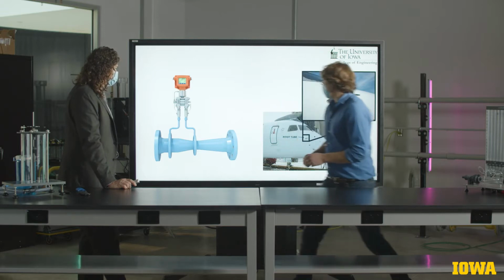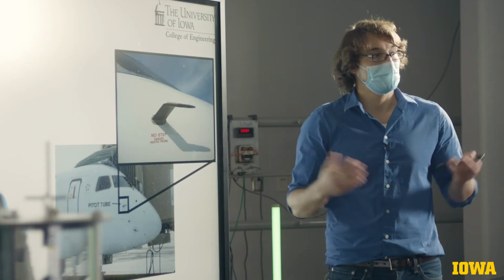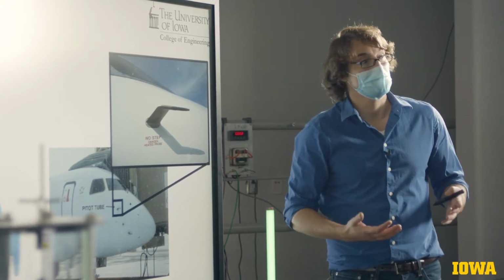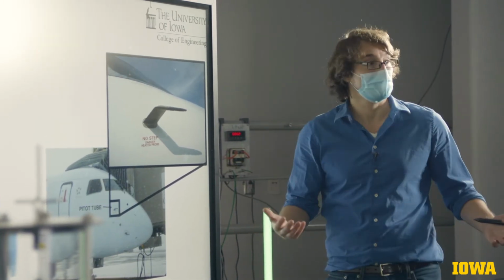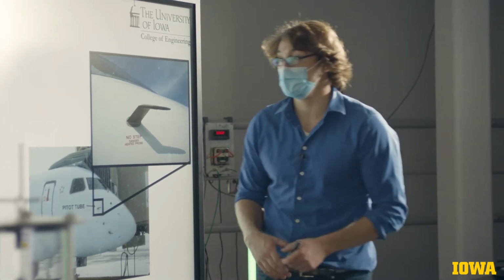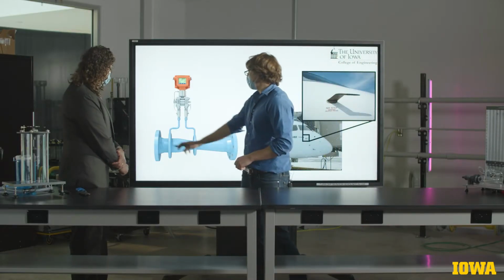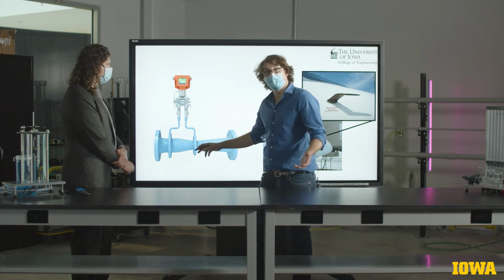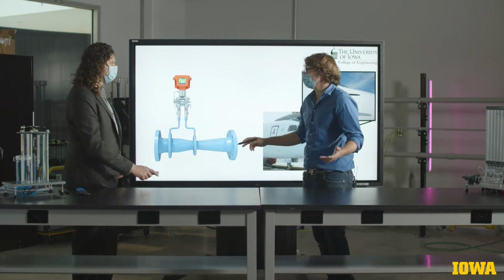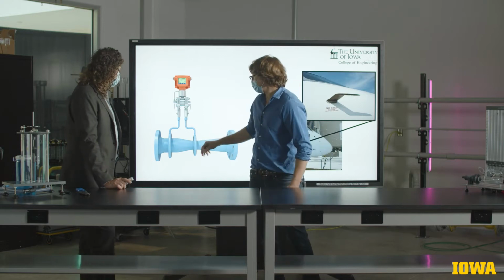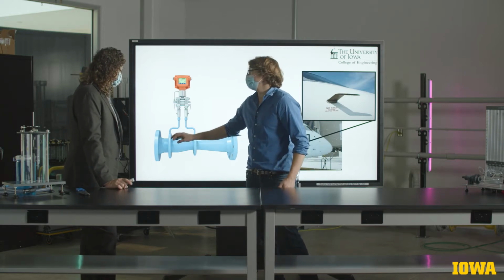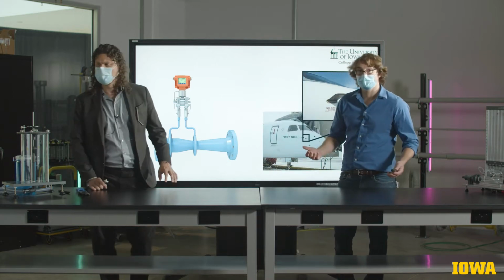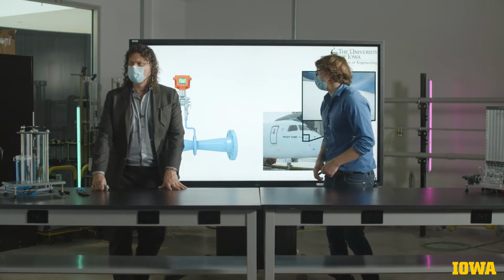The Venturi meter and the Pitot probe both share common lineage. That is, they both use the Bernoulli equation in order to infer what the flow velocity is. In the case of a Venturi meter, there's a contraction where the flow speeds up, and with that increase in speed comes a reduction in pressure. So by measuring the difference in pressure between the base flow and this constricted flow, we can find the velocity of the flow through that section.